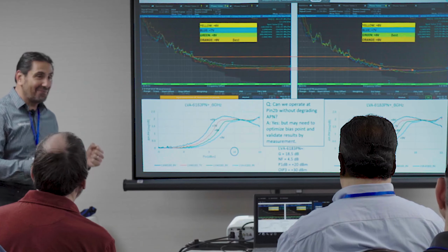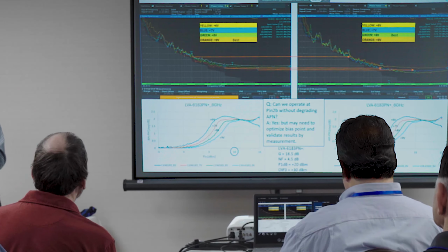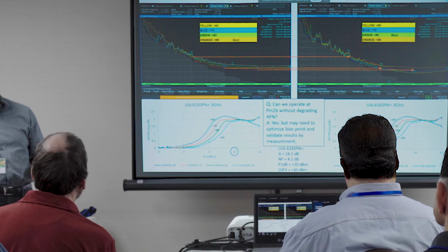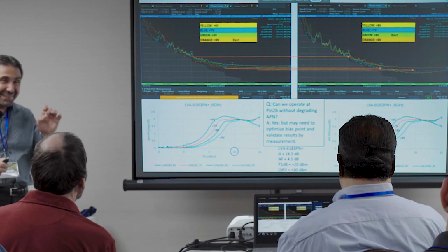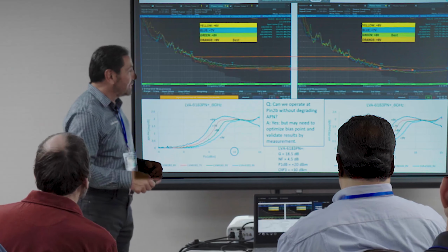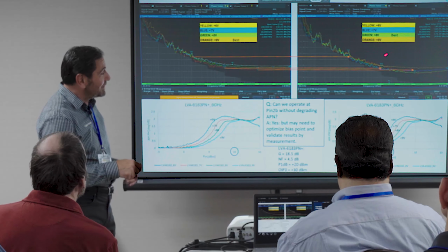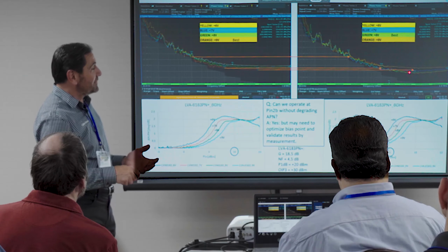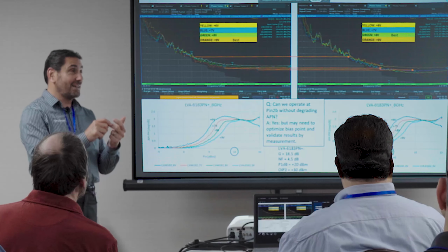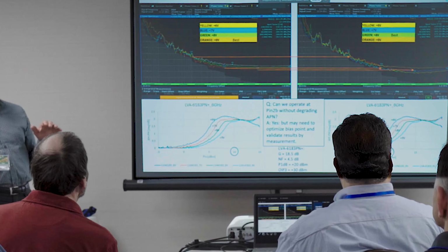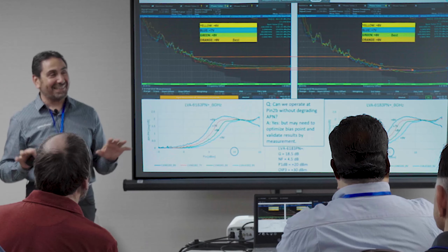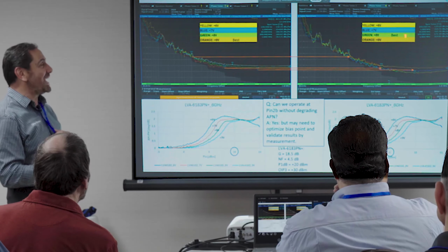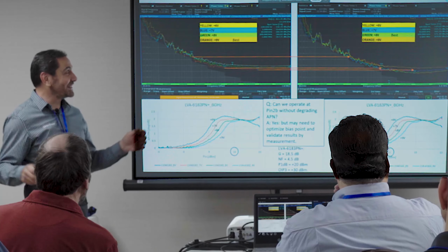All right, if you're down to this level of gory detail, you don't want a connectorized model. You want a test board so you can play with whatever voltage you want, set the current to whatever you want. That's what they're intended for. If you want to just see how they work in your system, use the connectorized. If you want to get into the nuances, you really need something like a test board. And look, you definitely see an improvement here. Maybe I'd run this guy at 8 volts. I go back, all right, 8 volts, this current, this kind of power with no resistance. I'm okay. We spec these parts very, don't tell anybody, very conservatively, all right? So you make your own calculations and you'll find that you can most likely operate pretty much wherever you want. And the part's still going to last forever.